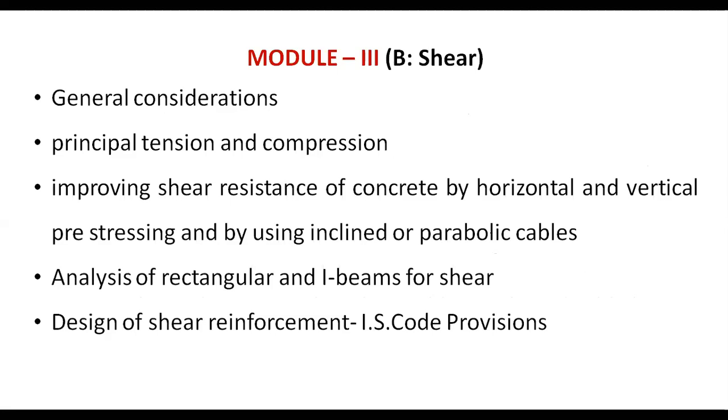So here, particularly shear, in the sense we are going to discuss general considerations of shear in pre-stressing elements, what the principal tension and compression are, and how we can improve the shear resistance of concrete. I mean, pre-stressed concrete by horizontal and vertical pre-stressing methods, or by using inclined or parabolic cables.